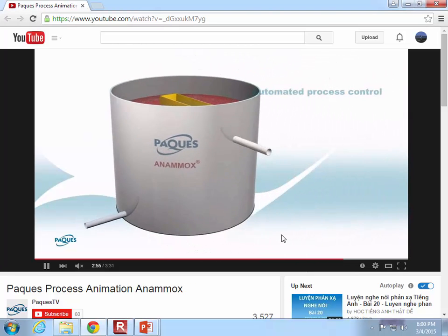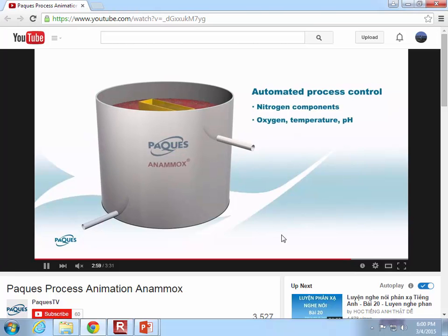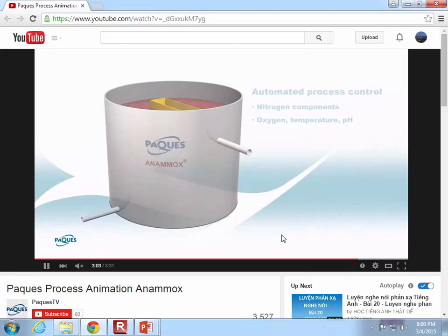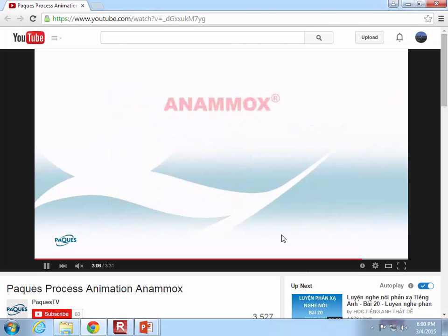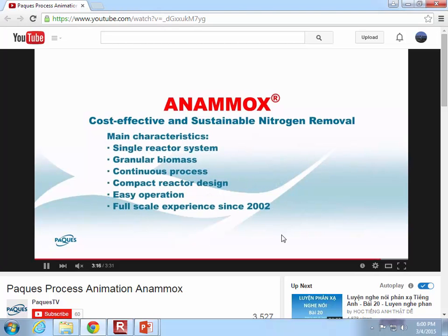So the same kinds of principles apply as in a traditional aerator clarifier, but it's kind of neat in this case that they don't need a whole separate clarifier. Because it's a granule, it's really easy to settle and strain, so they don't have to have a clarifier downstream. They also don't need to oxygen-starve the bacteria because it's happening in a steady state kind of thing.